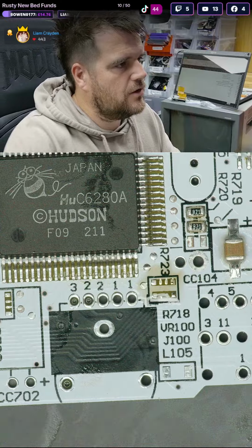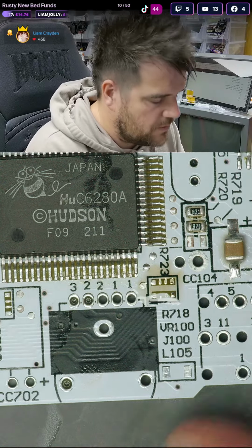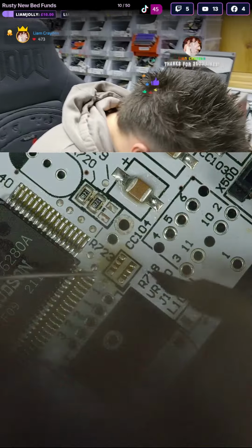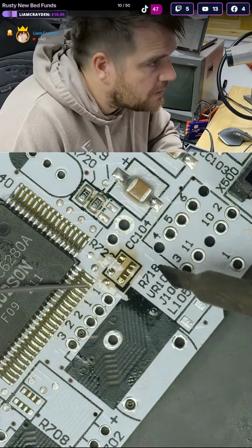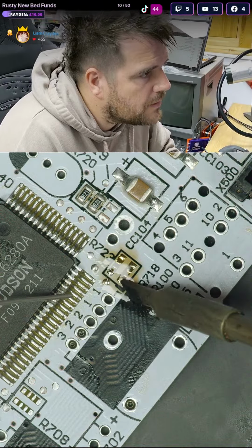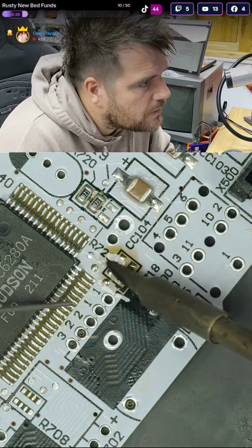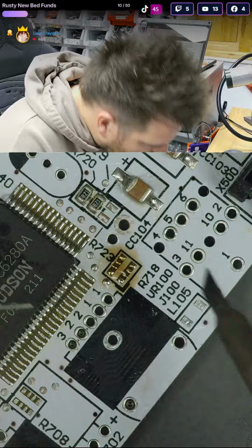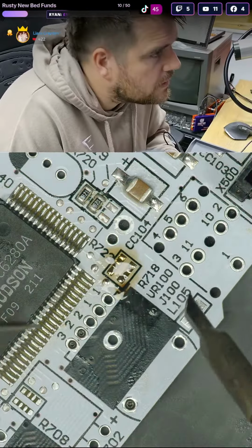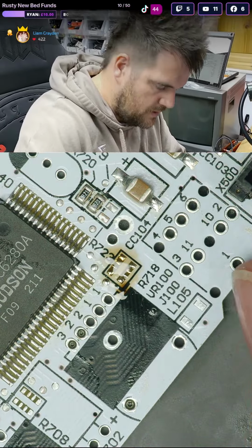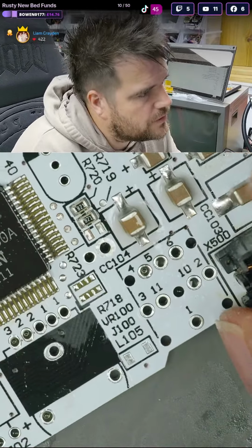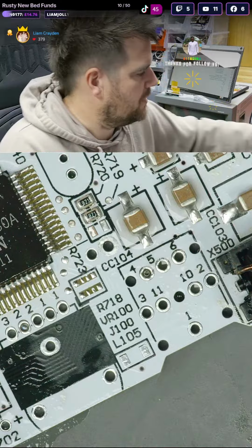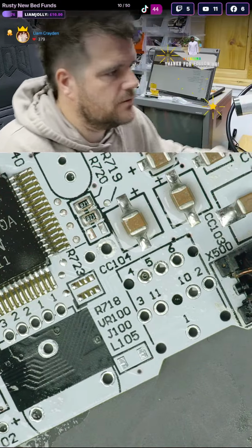So these pads here are basically 4 resistors in a row. They're usually 10k on quite a lot of them, and they're common to fail and stop the game loading. So if we pre-tin them pads, and is this iron working yet? We ideally want these to go over, otherwise hand soldering 4 individual resistors is a pain. I'd probably end up just ordering the resistor packs and waiting if so.